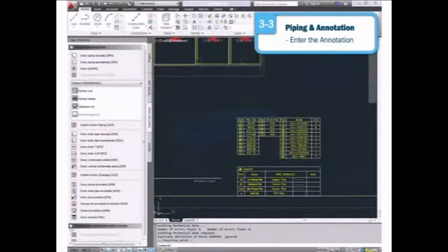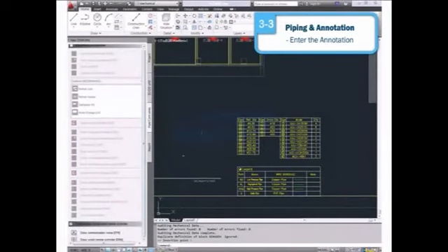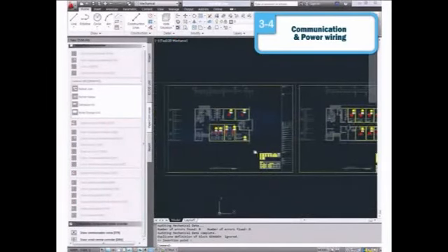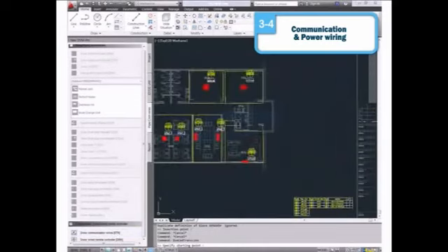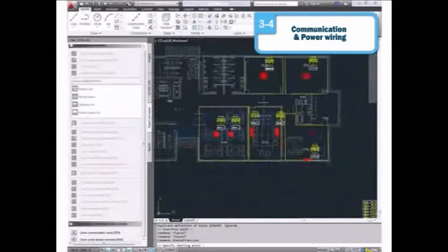When you reach the communication wire and remote wire step, all the pipe drawing will disappear. For communication wire, you may click Draw Communication Wire icon to connect indoor unit and the outdoor unit. If you move the cursor near the indoor unit, connection point will be created automatically.